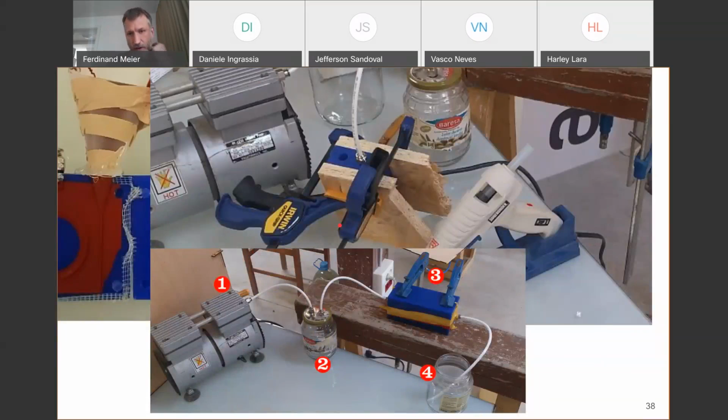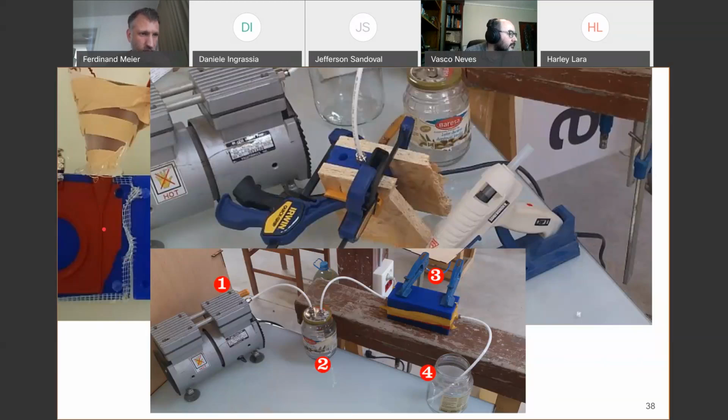And yeah, here's some more pictures. I had some students in Barcelona or in Valdaura, and they actually wanted to make the rubber part. So they were not interested in making the rubber part was already their final piece. So they made a two-sided mold, but there's no way the silicone will just flow in there and fill the whole mold, because it's just far too viscous for filling